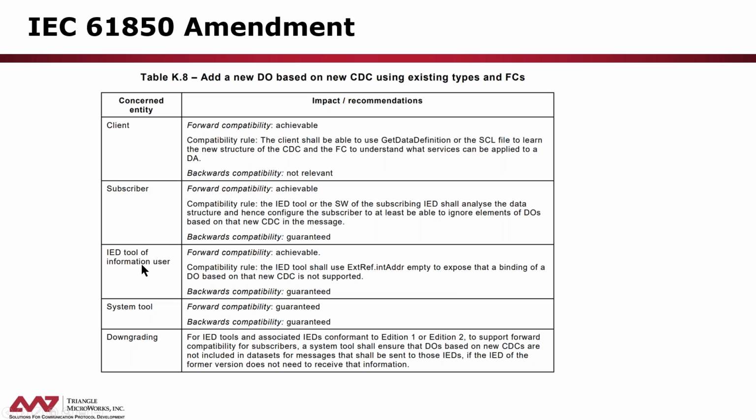If I'm the IED tool, so each IED in the 61850 system has a configuration tool and then access. It interprets the SCD file, configures the device. Again, essentially the same situation. Forward compatibility is achievable as long as I design my tool to understand the possibility that comes here.